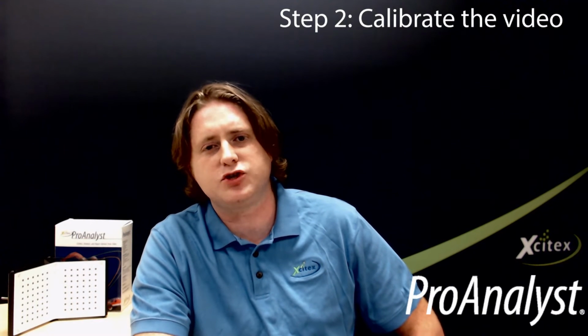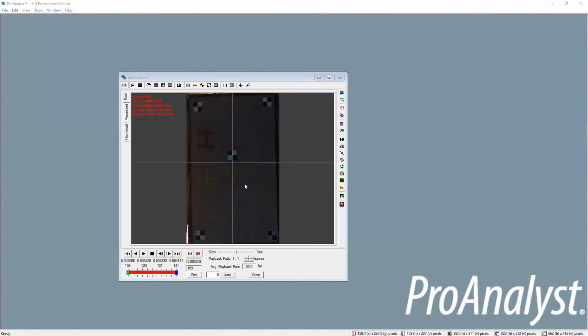The more accurately your video is calibrated, the more accurate the results from ProAnalyst will be. This is arguably the most important step of the capture process and something you should think of every time you set up a shot. Most videos need to be calibrated in two ways: temporally and spatially, or distance and time. We can see that this video has already been temporally calibrated. This is typically done at the time of recording and is reflected in the frames per second that the camera